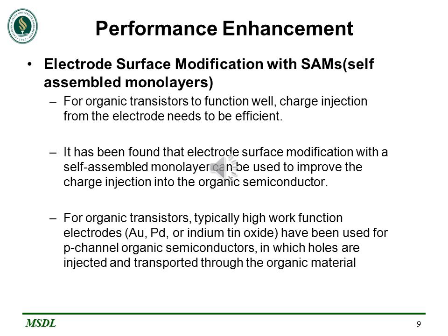So basically here we have electrode surface modification with the self-assembled monolayers. This is basically the electrode surface of the flexible transistors, and for organic transistors to function well, charge injection from the electrode needs to be efficient.